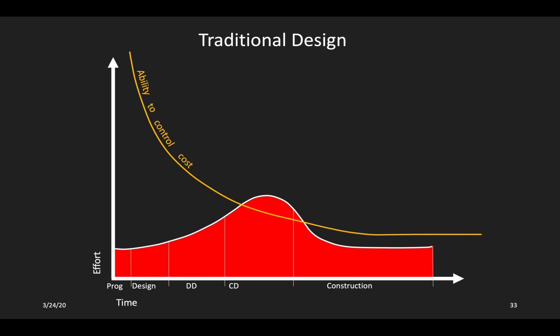So that cost will be lower. But if you're already in the construction phase, you already put in the concrete, and you start building the upper structure, and now you realize there's actually a problem. The reinforcement we used in the foundation is not strong enough. Now we need to tear up the foundation and start all over again. That's going to be very costly.